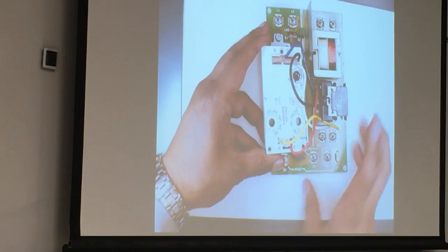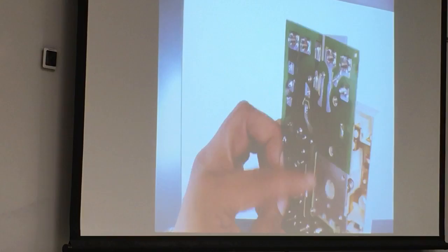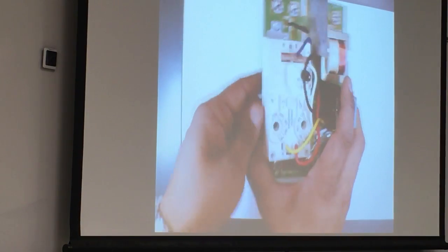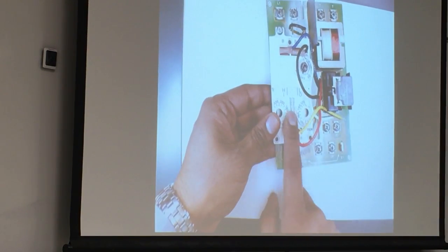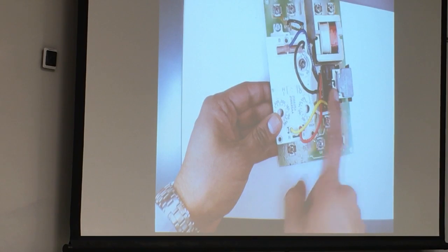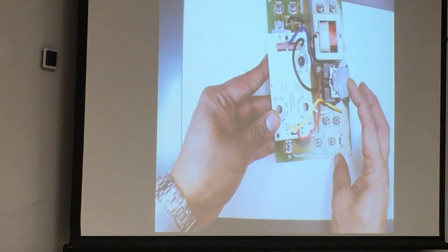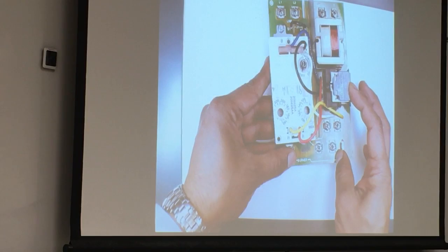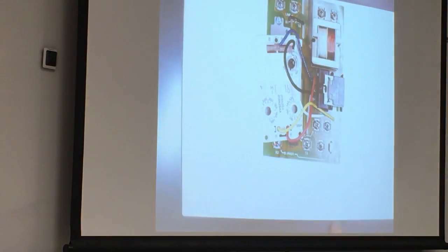And if the temperature inside the water, this water is connected to a sensor. The sensor goes into the tank. If the water is not within the limit, it will activate the relay. The relay will pull in, and the boiler will turn on. So main circuit, sub-circuit, another sub-circuit.